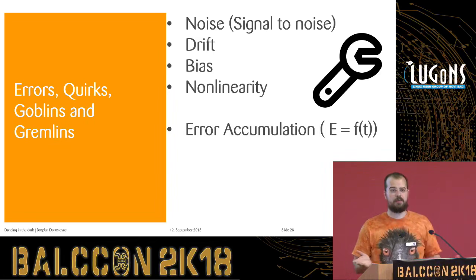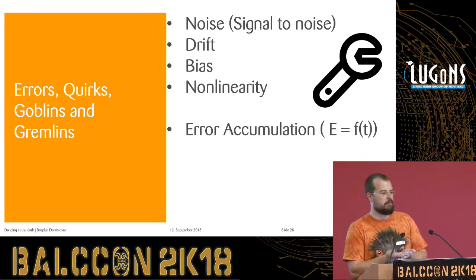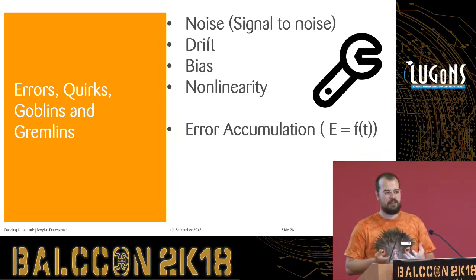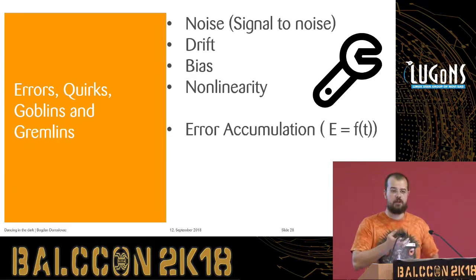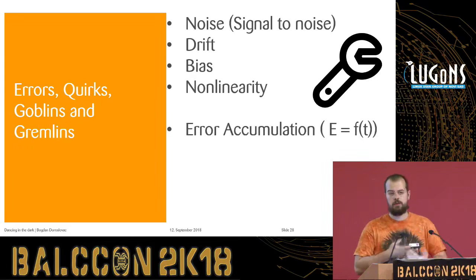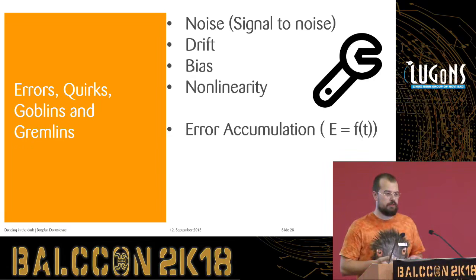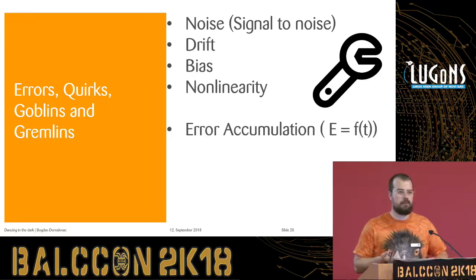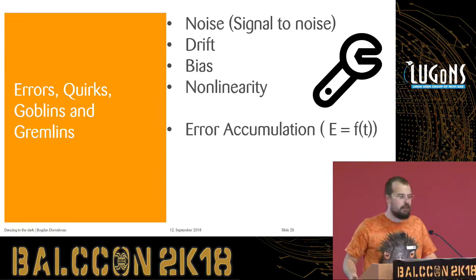Actually, physical drifting was first described precisely in the self-sustained, self-balancing platforms. People would notice that over time, gyro-gimbaled platforms tended to drift physically, or to change their position because of some small imperfections, like, for example, friction, which is an actual thing in the world around us, maybe not in physics, but in mechanics tends to have quite an impact. Everything is biased, not just people, gyros as well. And there are a lot of non-linearities. You never know how the device will behave.